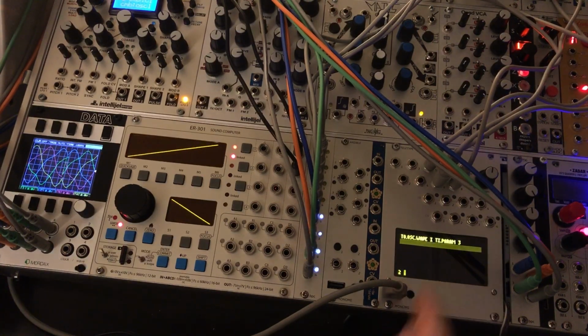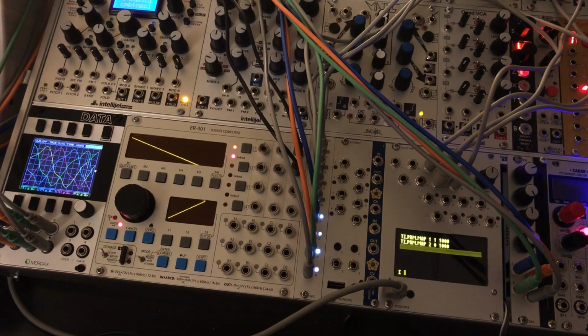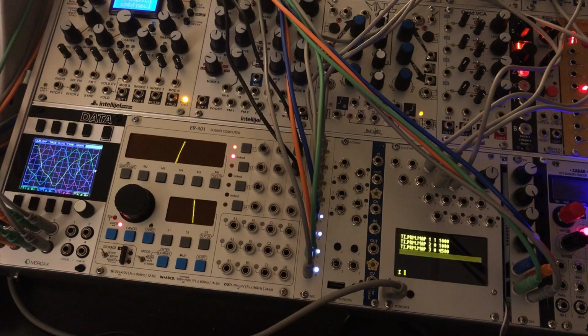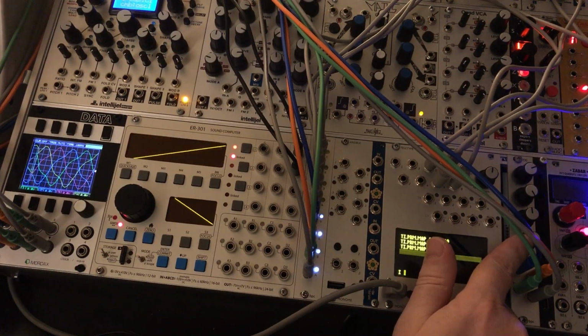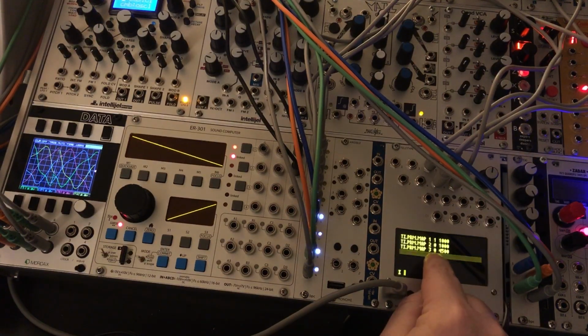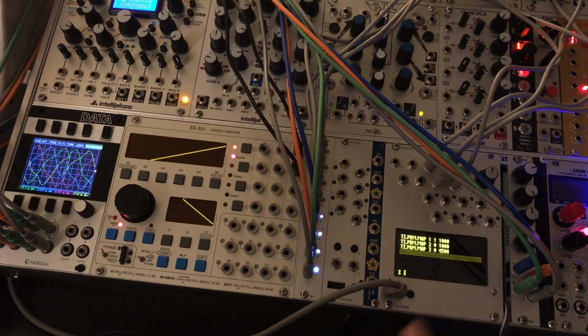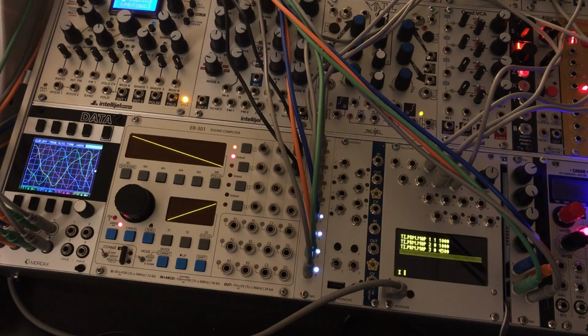So let's set up the value range for param3. Again, we'll put this in the init script. Let's do ti.prm.map3, and we'll start with 0, and I'm not sure the exact number here. Let's try 4,500. So these ti param maps are essentially, if the knob goes from 16,383 plus to minus, instead of doing that, when it's at a minimum here we're going to read 0, and when it's at a maximum, we're going to get a reading of 4,500, and all the values in between will just be between 0 and 4,500.